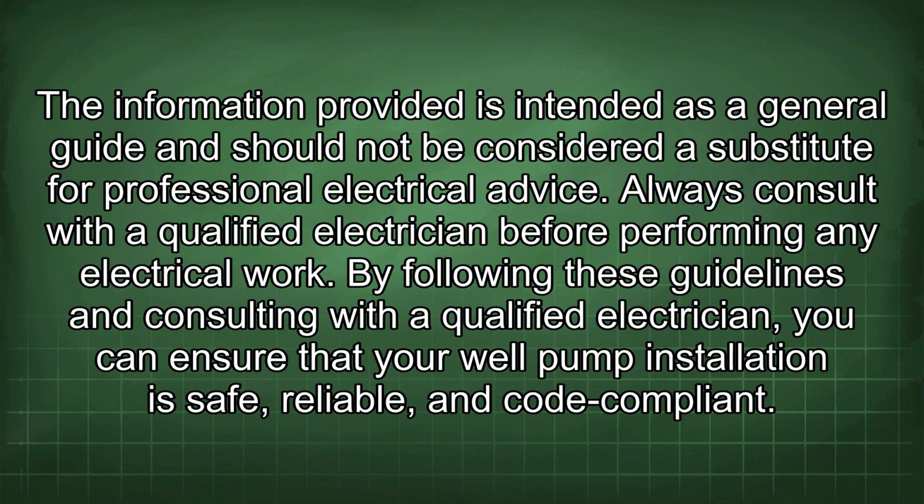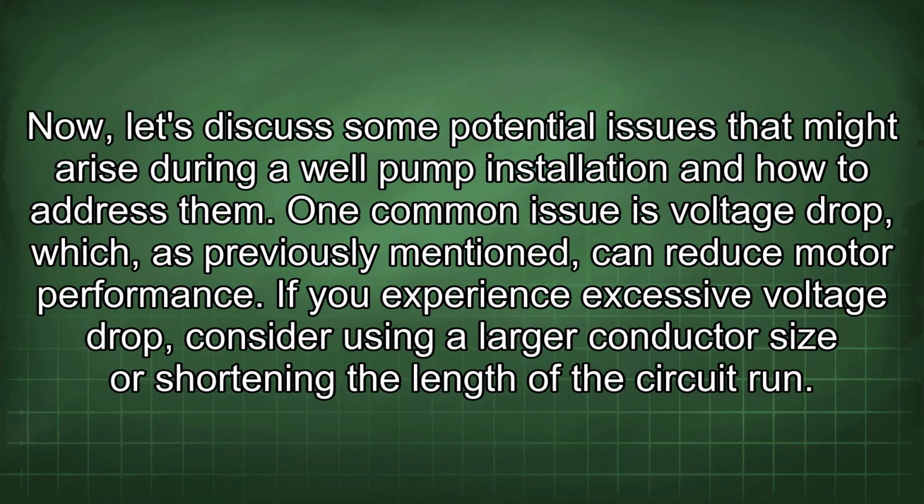By following these guidelines and consulting with a qualified electrician, you can ensure that your well pump installation is safe, reliable, and code compliant. Now, let's discuss some potential issues that might arise during a well pump installation and how to address them. One common issue is voltage drop, which, as previously mentioned, can reduce motor performance. If you experience excessive voltage drop, consider using a larger conductor size or shortening the length of the circuit run.